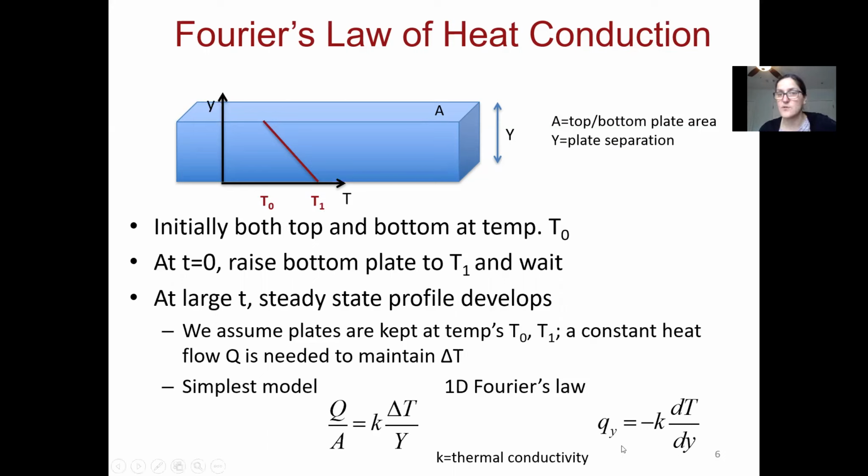So when I actually put this in a coordinate system, the Y component of this linearized heat flux, Qy, is negative K times the derivative of T in the Y direction. Again, because the derivative of T lives in the coordinate system and aligns with it, but every coordinate system points from lower to higher, we have to have that minus to make things physically right, because heat flows from higher to lower temperatures.